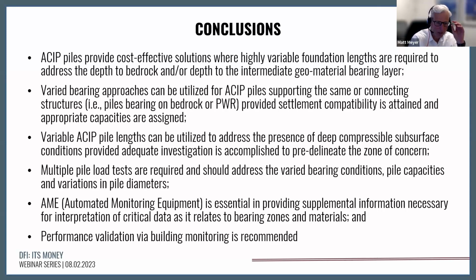I hope that you agree with me and you see me illustrate that auger cast in place piles can provide an effective solution where we have highly variable foundation, highly variable bearing materials such as the Mercedes-Benz Stadium, where we have variable depth of bedrock, variable depth of partially weathered rock, or embedded deep compressible subsurface materials that requires proper pre-delineation so that we can have settlement compatibility.